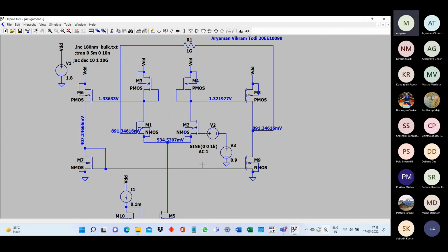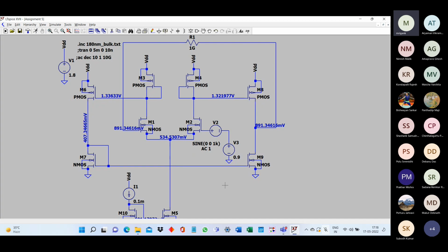From the DC point of view, I don't see much problem. The DC voltages are correct. You can see that the input voltages are very close together. They will become even closer if your gain is higher. Right now the gain is relatively lower. Therefore, you have the voltages showing some error. That's why I had asked you to notify the error also. If your gain is poorer, your error will be larger. As you increase the gain, the error will disappear. So is this clear to everyone?